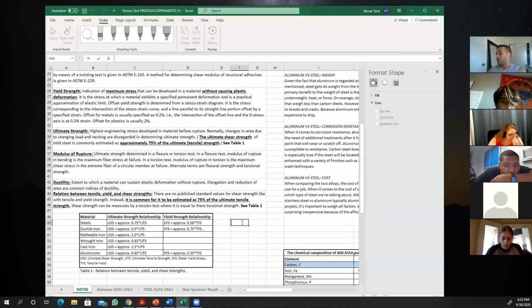So for the tensile yield strength, you're going to go back to your previous report and find the yield strength. If you multiply by 0.58, your yield strength should be the same as what you get on this experiment, if they are the same material. If I'm testing 36 KSI steel, let's say, and I want to know the torsional yield strength before I do the experiment.